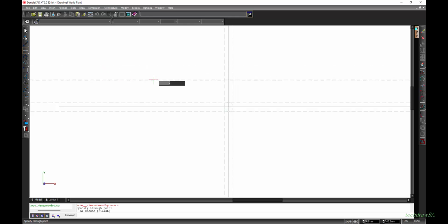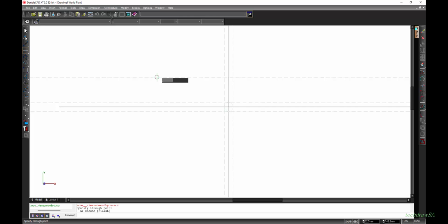But here, please differentiate between the construction line of the CAD program, that's for all CAD programs, and the construction line that we refer to when we do our constructions on paper drawing. Good, so that difference must be clearly understood. I like to refer to this as a water line. So if I do refer to the water line in the future, it means it's the CAD construction line that I am using.